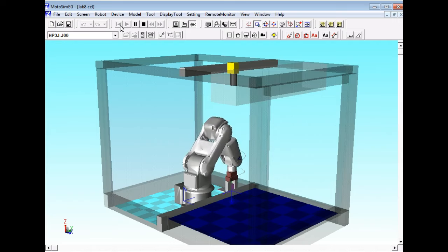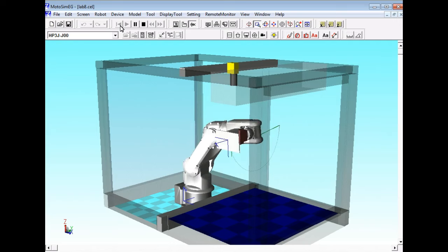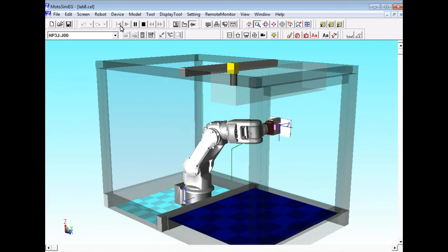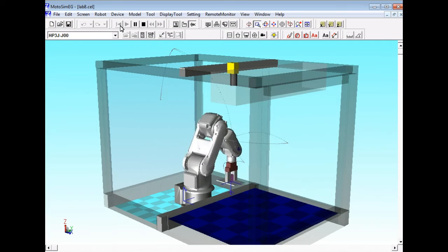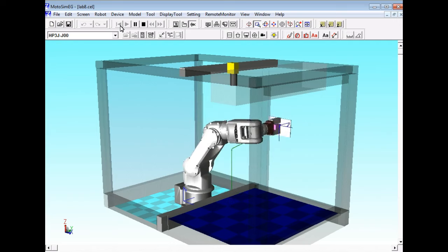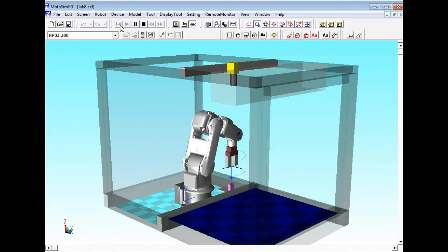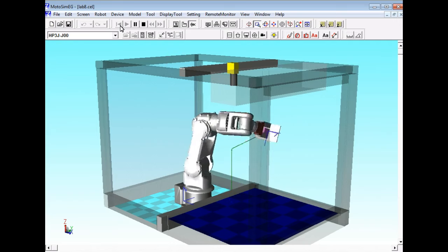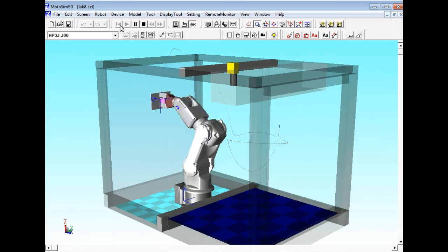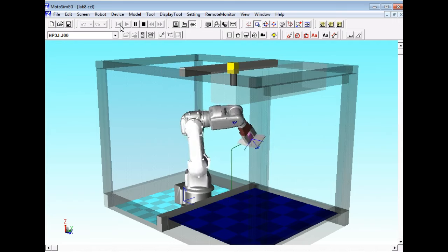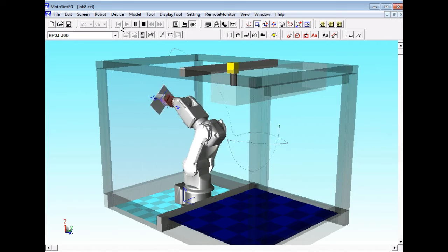doing offline programming. Now, offline programs are still not perfect, because your offline program is only as accurate as your 3D model. So if a welder goes out there and adds something, or they decide to do that, and the programmers don't add that to their model, then we're still going to run the program, but we still got to watch it, and we got to see what it did on the simulation. If it does what it does on the simulation, then we're okay, but we can also always touch the program up online, right? Does that make sense?